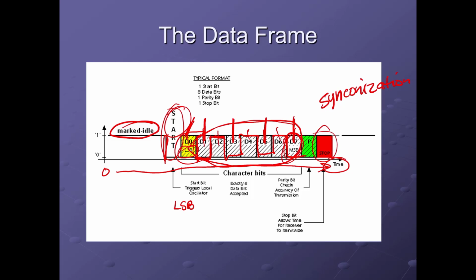Now that's important, because if you've got that series of bits and you don't know which is LSB and MSB, you won't be able to properly interpret it to know what the meaning of that character is. Now I will address parity right now. Most data connections now don't include parity for error detection of this data. And really it's because now the terminals on either end of this asynchronous connection are smart enough to detect errors without the use of parity.